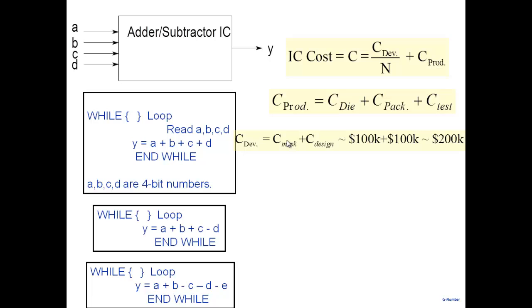Roughly, if we are taking 180 nanometer as an example, there may be about somewhere between 20 to 30 masks required, and these numbers vary, they may cost you up to $100,000 for the entire masks to be made. So for your circuit, a custom set of masks will have to be made. They may cost you $100,000.